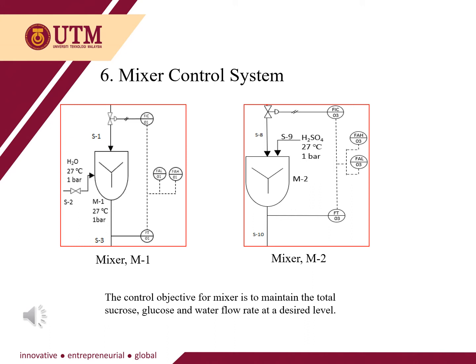Next is the mixer control system. This mixer is designed to mix the molasses with water before entering the fermentation tank for reaction. The control objective for the mixer is to maintain the total sucrose, glucose, and water flow rate at a desirable level.